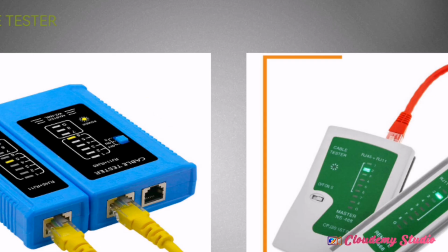Once you switch it on, the light will start ticking on these colors. You start matching. If you skip one number, then from the color code you'll be able to tell that, okay, you have skipped maybe, for instance, 2. Then you're able to tell that the orange color is not working in this network cable.